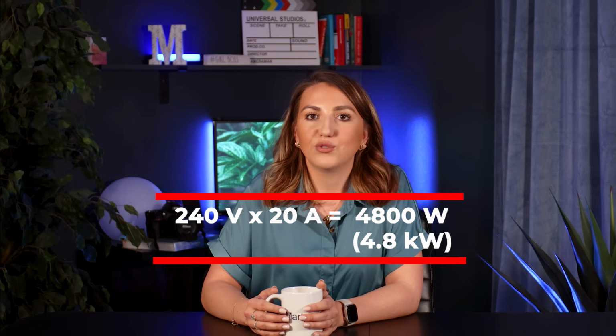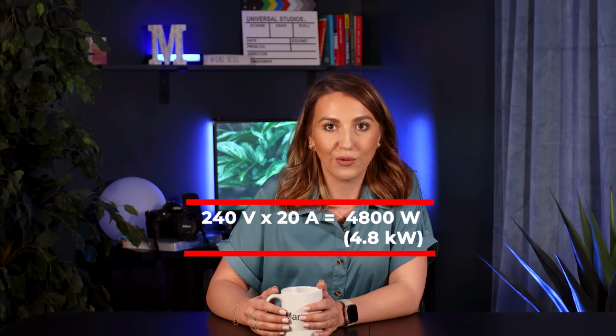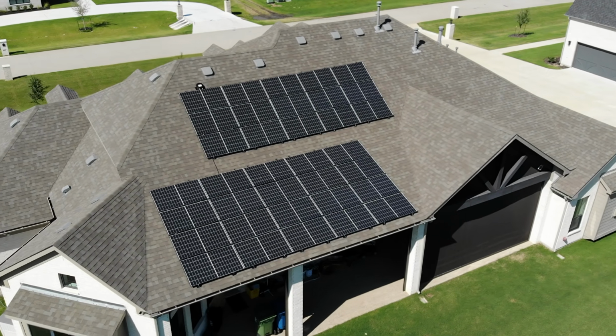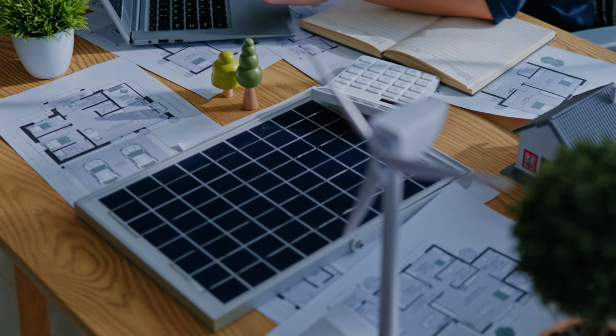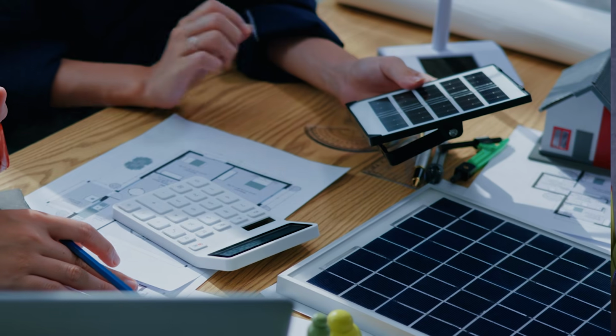So if you have a 240 volt circuit in your home with 20 amps flowing, that's 240 times 20 equals 4,800 watts or 4.8 kilowatts of power. In a solar system, your panels produce DC, direct current, electricity at a certain voltage, and then your inverter converts it to AC at the voltage that your home uses. Typically, that's 240 volts here in the USA. The whole system is designed to match the power needs of your home, which brings us back to the main topic, making sure that kilowatts capacity meets your kilowatt hour needs.